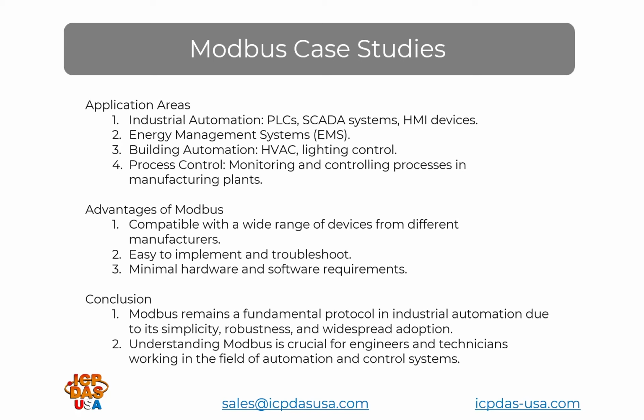Well, you do that by daisy chain. So essentially you're connecting all the data plus and data minus terminals separately. For instance, if you have one master device, you connect the data plus of the master device to the first slave device. And then from that slave device, you also connect that data plus to the next slave device and continue on until all the data plus devices are connected. Then I would start with the data minus from the master and go to the first slave and continue on. Ideally, you want to use twisted pair, but you just need two wires anyway. So if you use two colors and they're a short distance apart, there's not too much chance for confusion.